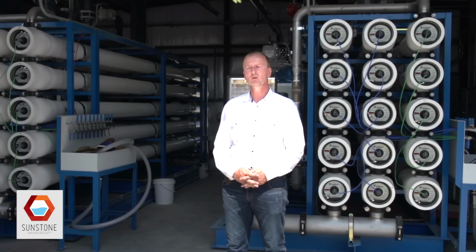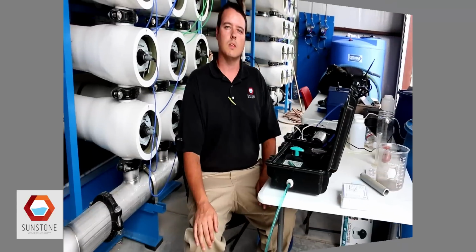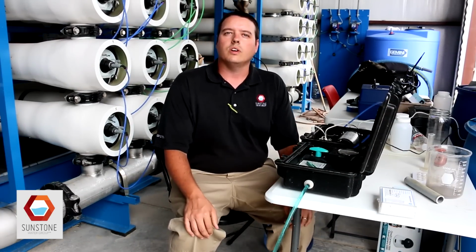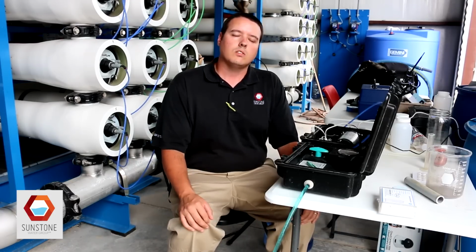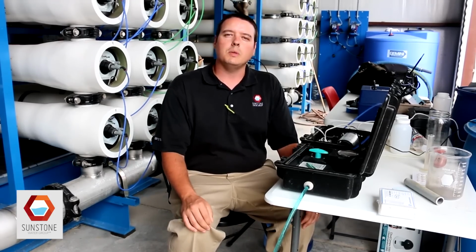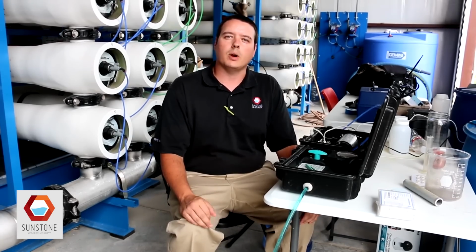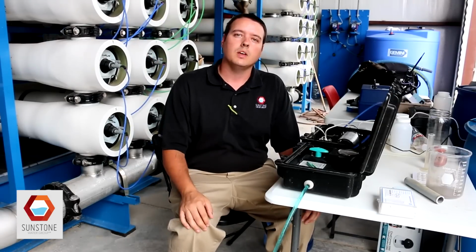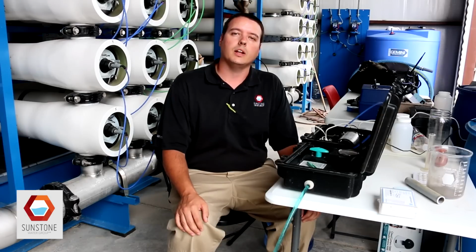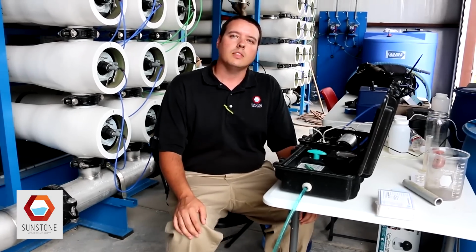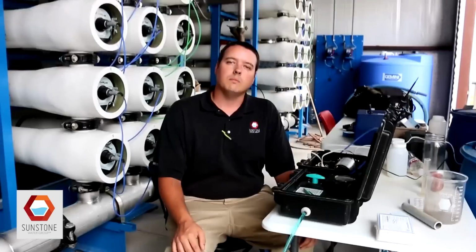You can actually do a quite simple small test that will show what and how the water actually will foul the membrane. Today we're going to run a series of silt density index tests, or SDIs. Silt density index is used to simulate water flowing across a membrane, such as in an RO system. And the SDI can give us an indication of how likely the water is to foul the membrane and how quickly it will happen. The higher the number of the SDI, the more fouling potential there is in the water.